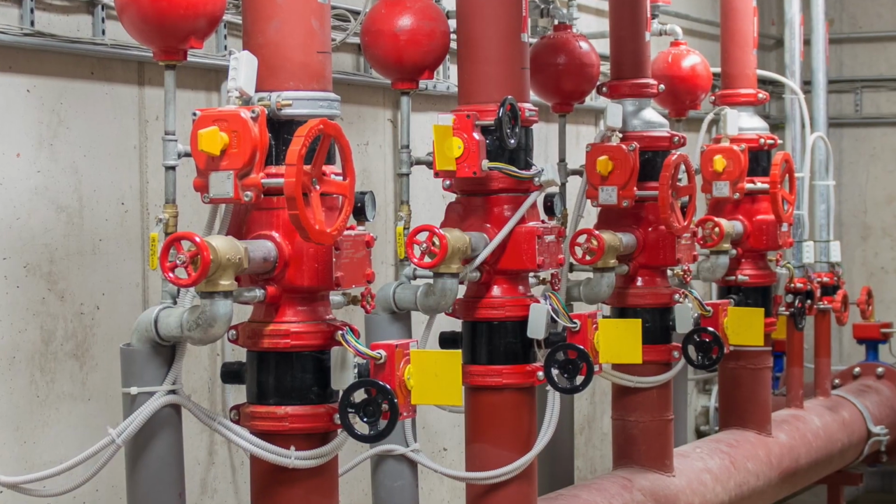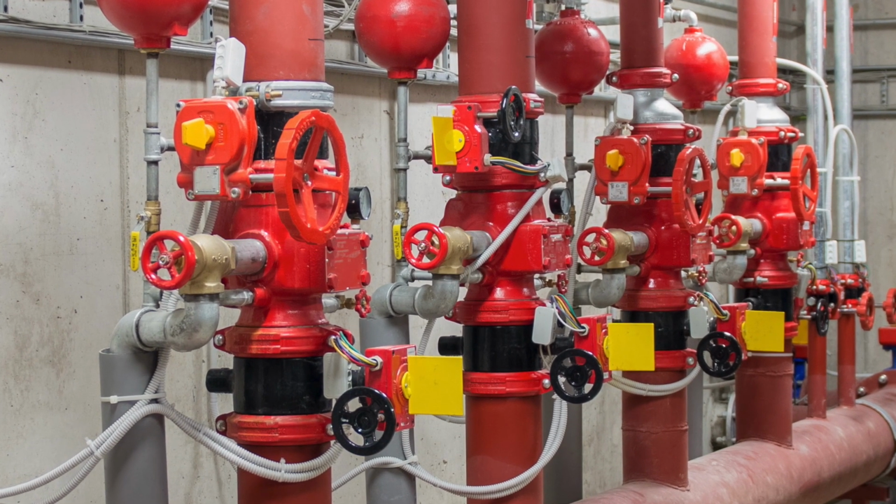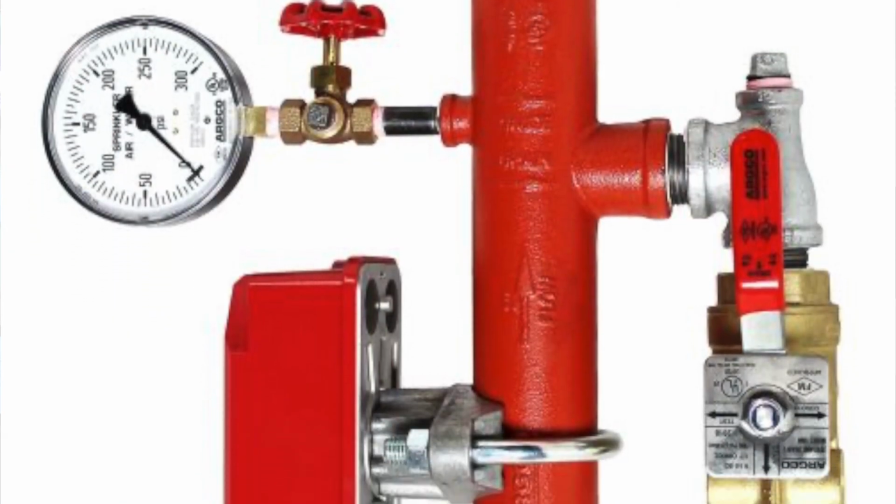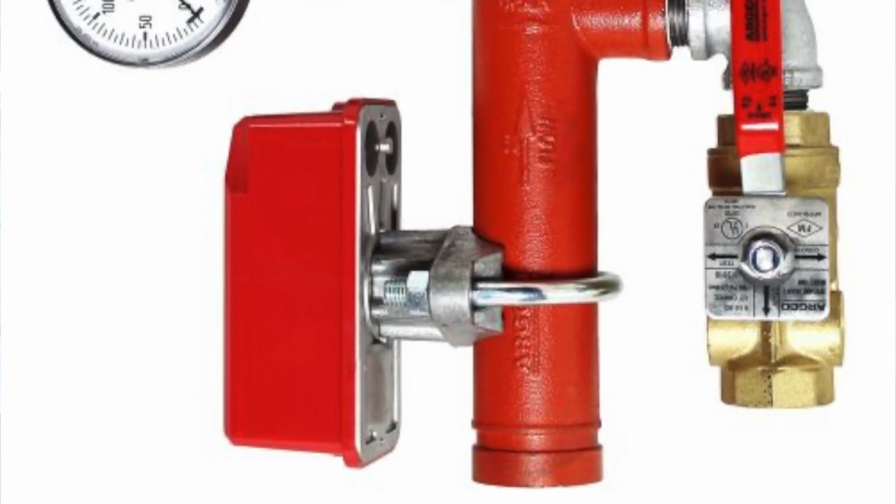Additionally, you can use fire alarm input modules to interconnect with a sprinkler system. A fire alarm will monitor the open and close position of a tamper valve. In short, a tamper valve is a door that holds the water back on one side. However, if that tamper valve were to open, then the water will start to flow. In the event that the water is flowing, we have another input module that we put on a water flow switch. This monitors the flow of water over a period of time, usually between 45 and 90 seconds.